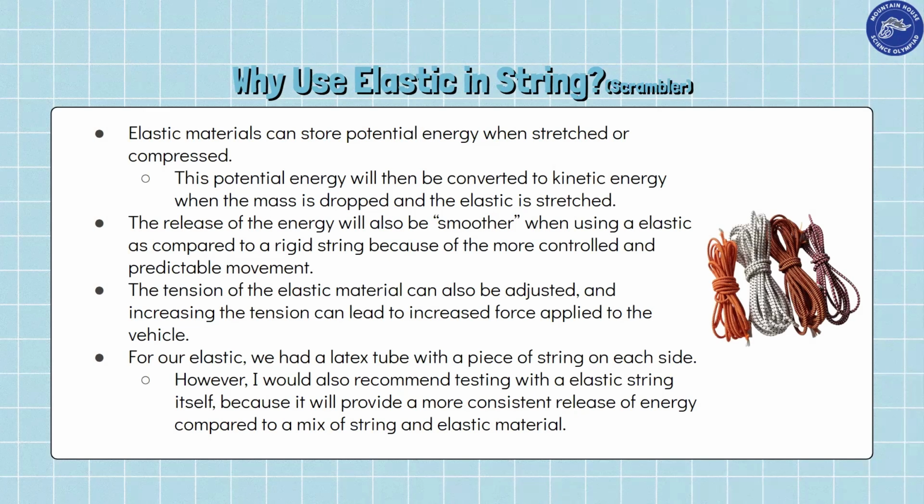Tension of the elastic material can also be adjusted, and increasing the tension can lead to increased force applied to the vehicle. The way you do this is, to increase tension, you'd maybe have a shorter piece of elastic material, and that would force it to stretch more. For our elastic, we had a latex tube with a piece of string on each side. However, I would also recommend testing with an elastic string itself because it'll provide a more consistent release of energy compared to a mix of string and elastic material.